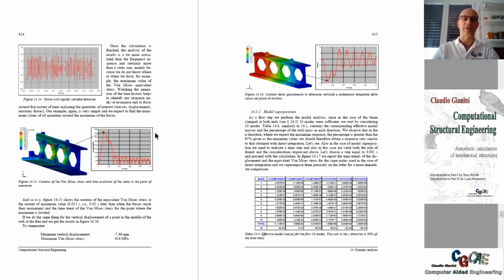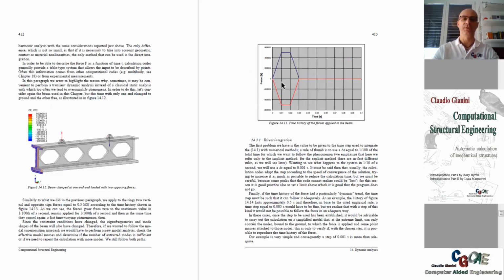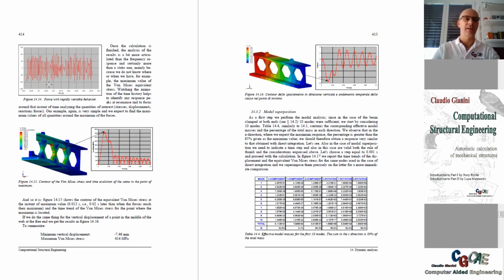Again, some advice is given on what time step to be used, because this is quite easy to understand. Of course, we need the time step to be small enough to be able to follow the time history of the forcing. But in this case, clearly we need to have a very small one, because the time history is quite complex.